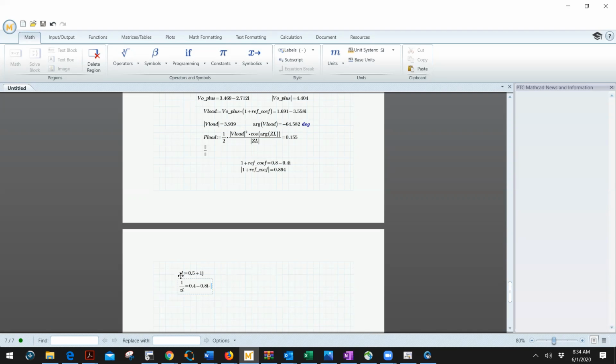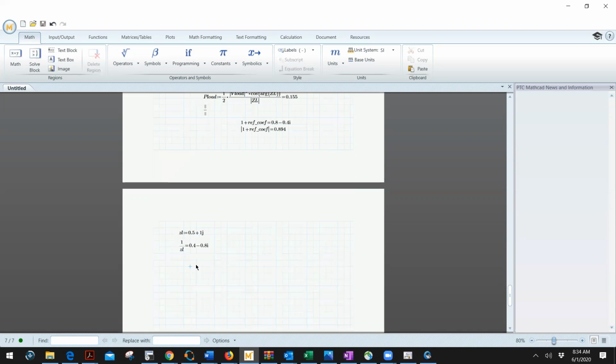Now, something I have to say, if this is the normalized impedance right here, and I hope, can you all see it right there? Remember the way we got that, we divided by Z naught. So if you wanted to know the actual Z a quarter wavelength away, you would say that the actual Z a quarter wavelength away would be equal to 1 over ZL, or looking at the Smith chart value, and it would be times 50, because that was the actual value of the characteristic impedance.